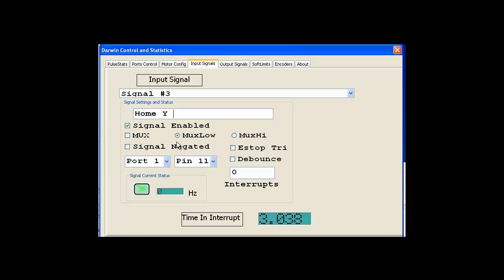There is mux low and mux high. This is for multiplexing signals. A single printer port can actually have more signals because it can share any pin with 2 signals, but that's for advanced users, and until such time that some breakout board can take advantage of it, there are only a few plasma type boards which can at the moment. You should leave mux unchecked and turned off.